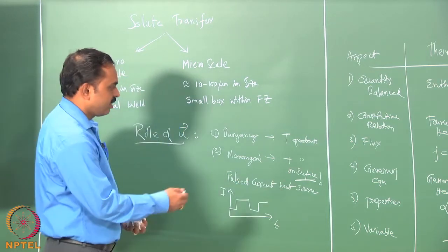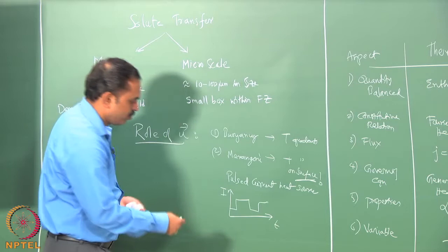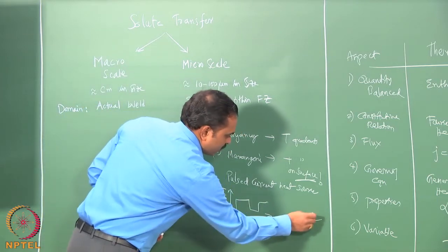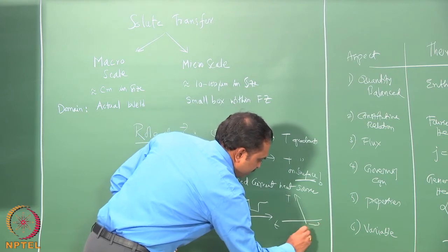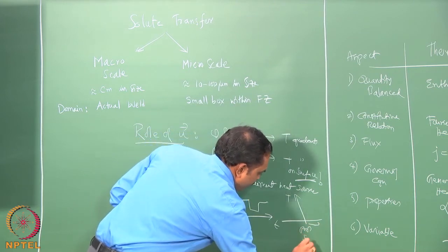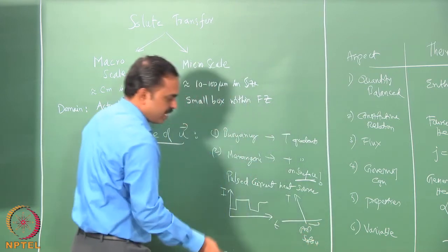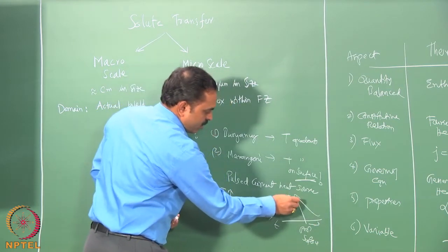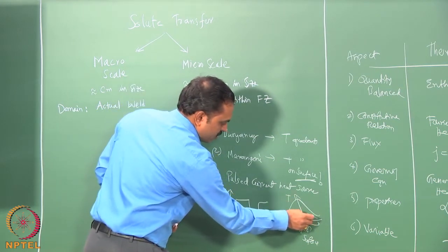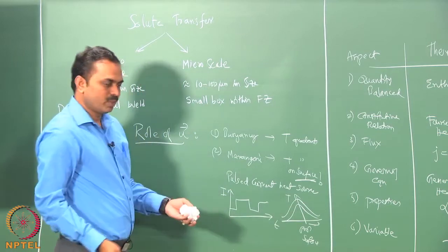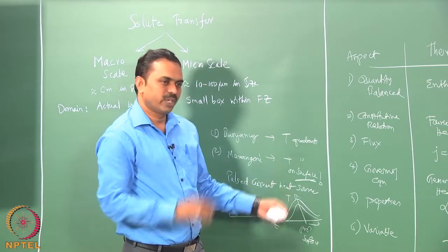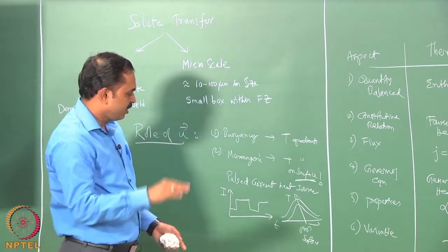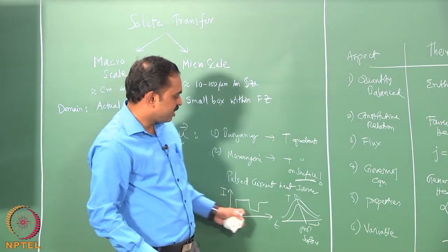In other words, the temperature gradient on the surface of the pool, if you were to look at the temperature as a function of distance on the pool surface, you would see that it may fluctuate between 2 appearances like this, sometimes sharp and then sometimes shallow, and it can keep fluctuating between these 2 as often as the pulsing frequency.